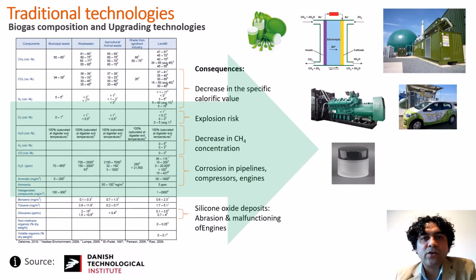Besides the high content of methane and carbon dioxide in biogas, the rest of its composition differs greatly depending on the feedstock and operational parameters during the anaerobic digestion process. The gas composition is mainly determined by the type and quality of the biomass, as well as the conditions of the gas generation process. Biogas contains mainly methane and carbon dioxide, but it also contains trace compounds such as hydrogen sulfide, halogenated compounds, and volatile methyl siloxanes.